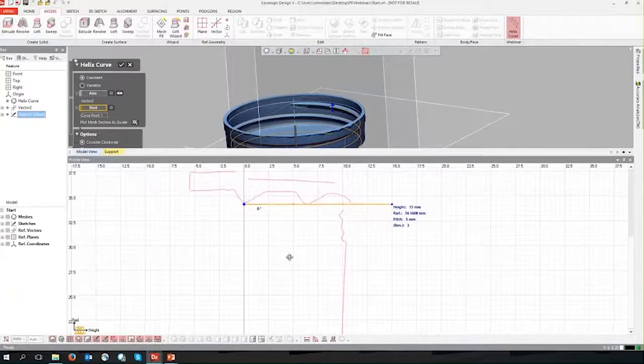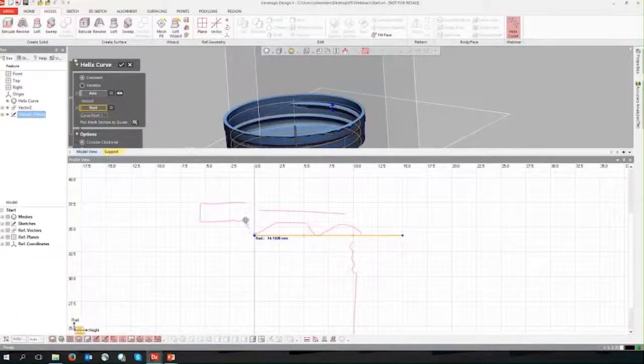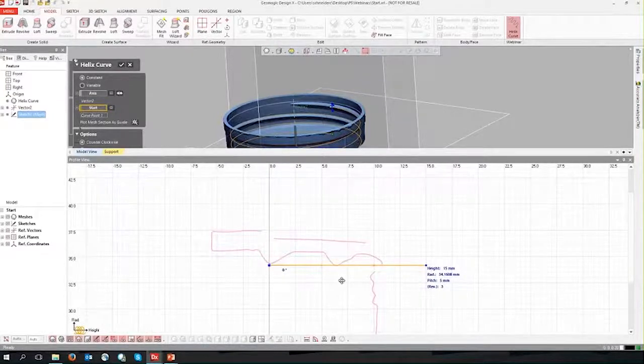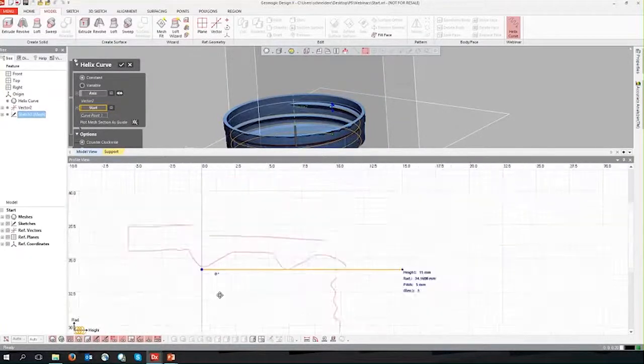So we can see we started our 2D mesh sketch with these two threads, and this cross-section also shows me this information. If this thread got bigger or smaller with the radius, this is a visual representation of that as well. This plot is set up where we have the height along the x-axis, and the radius along the y-axis. We have this little key at the bottom. It starts at 0. That's what this center line, or this darker gray line, is for. Then we have these numbers at the top, which can be helpful. And we can resize the bounds by just zooming in and out.